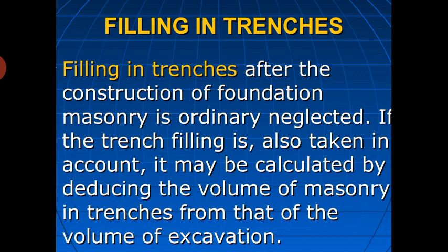Filling in the trenches after the construction of the foundation masonry is ordinarily neglected. If the trench filling is also taken into account, it may be calculated by deducting the volume of the masonry in trenches from the volume of the excavation. So maybe when you are doing the trench calculation, that has to be taken care of.